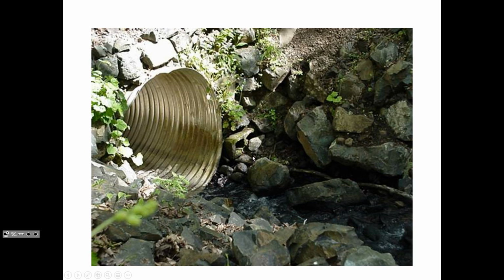Sometimes it's just as simple as a corrugated metal pipe that's been buried, and these pipes are kind of meant to flex a little bit. They get their strength from the fact that the soil compacts in the haunches below that curve, and so you'd think that it would crush, but you could have hundreds of feet of soil and rock above the culvert, and the forces just kind of pass through and around the culvert and don't crush the pipe in a way that you might expect, because as it deflects, it gets additional strength.